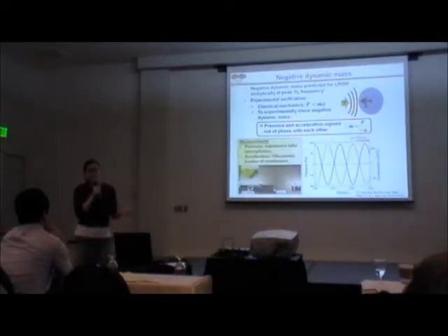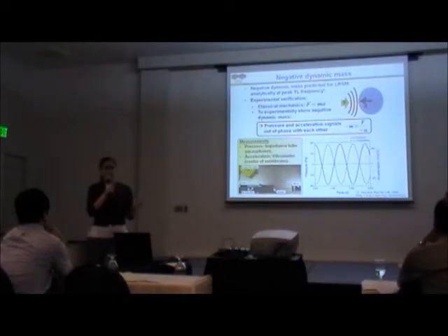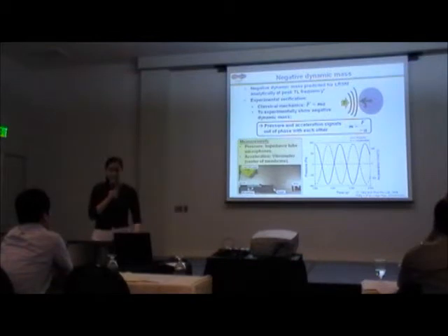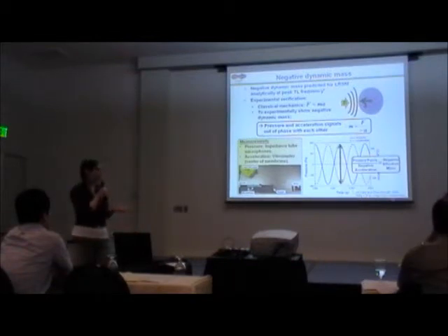In order to do that, pressure was measured using the impedance tube microphones, and the vibrometer was used to measure the acceleration, pointed at the center of the structure where the mass is. The response is shown here, so you can see that the signals are in fact out of phase with each other. And this results in a positive force, negative acceleration, and negative effective mass response.